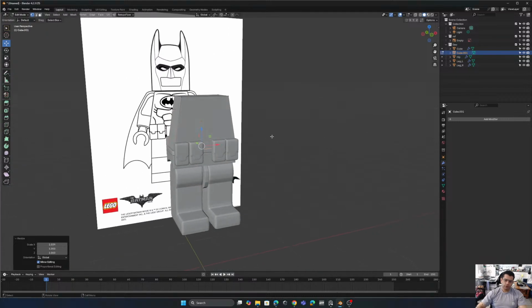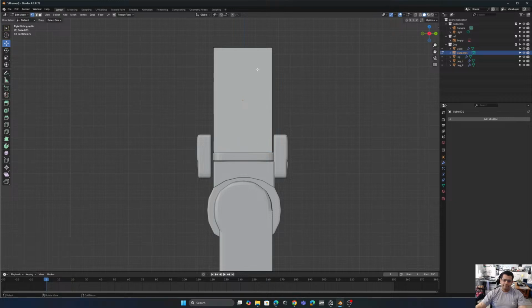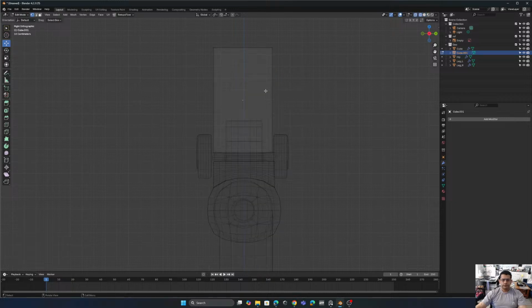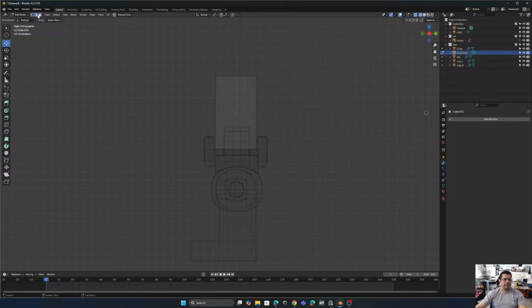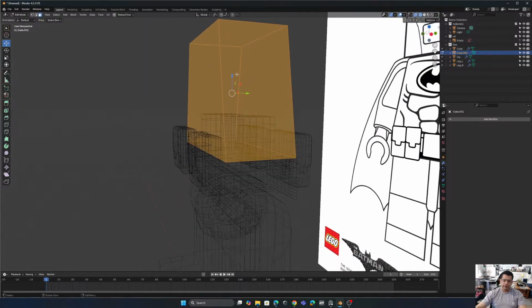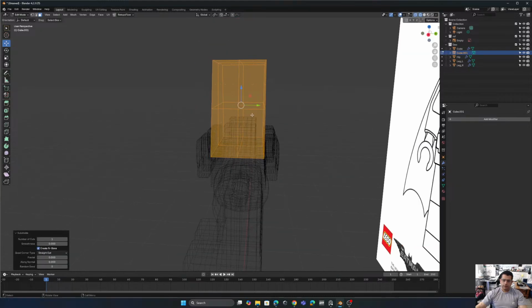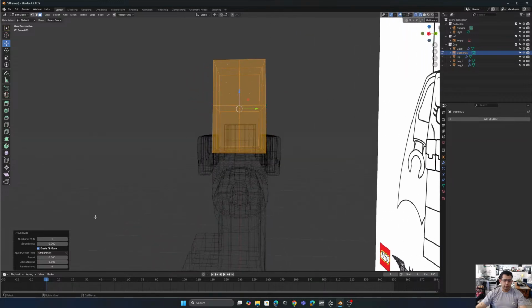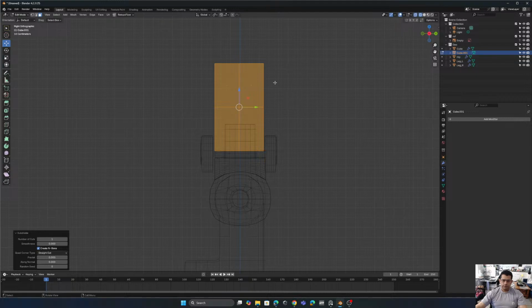So we're gonna go to side view, Shift Z to go wireframe, face mode here, or pressing 3 on the numpad. Select everything and subdivide. There you go. I think something over there is gonna be helpful. Let's see how many faces. No, I prefer that one. Just one subdivision. Enter.